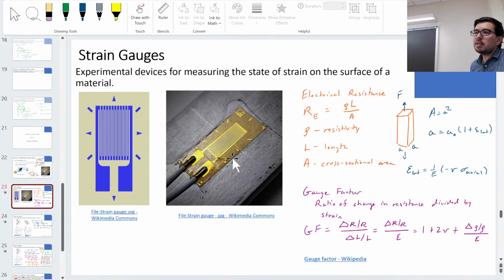There are other techniques that people use for measuring strain, and there are image-based techniques. There's something called digital image correlation, which is a technique where you have a lot of dots, and then you have a camera, and it's actually able to measure the relative motion of those dots. You have acoustic methods as well, and those techniques can be effective at measuring how much tension is in play too.